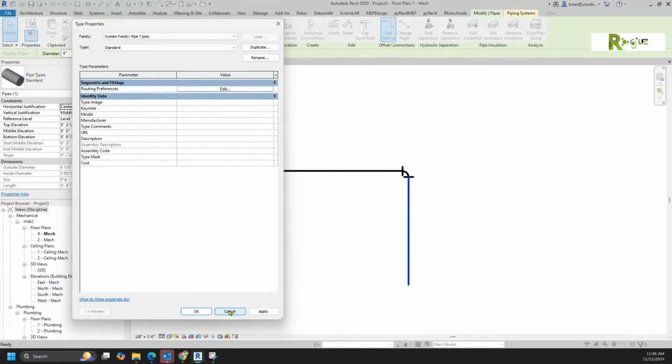That's what I showed you to do. But it still doesn't put a flange at the first 90 once you change that pipe type. It won't. It hasn't for me. So maybe you have to see something different.